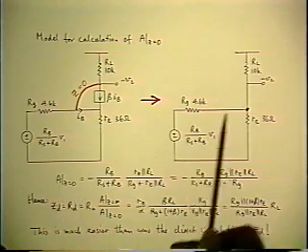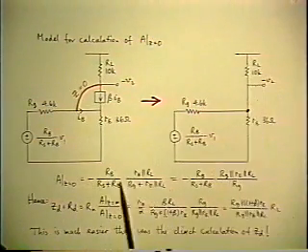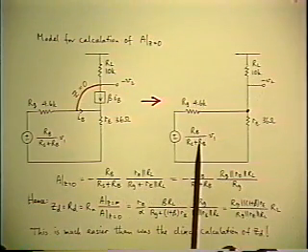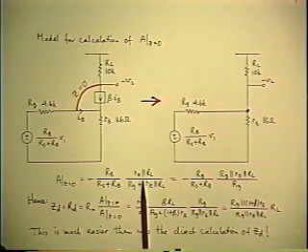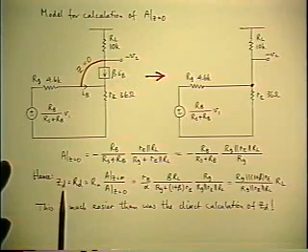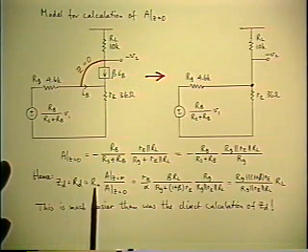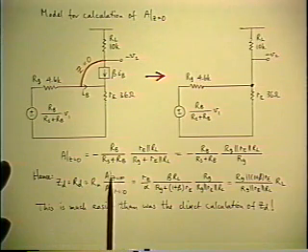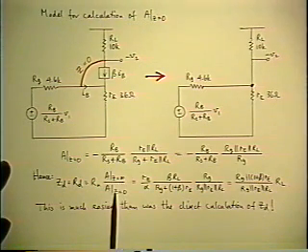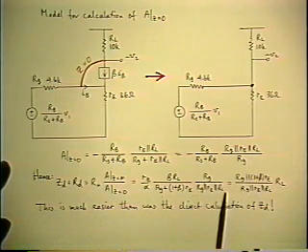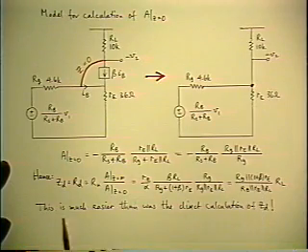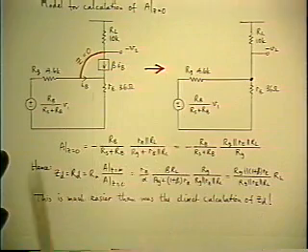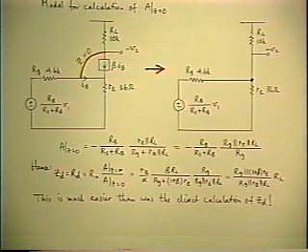So here it is. The gain when the Z is 0 is the divider ratio from the Thevenin equivalent that you have to begin with, and then the other divider ratio that comes out of the circuit model, which is this. So then, using the redundancy relationship to find Rd, it's equal to the Rn that we know already, multiplied by the ratio of the midband gain that we started with, divided by the gain when Z is 0 that we've just calculated. And there's the answer, which is a lot shorter than that long derivation with the circuit reduction and then still quite a few lines of algebra to deal with.